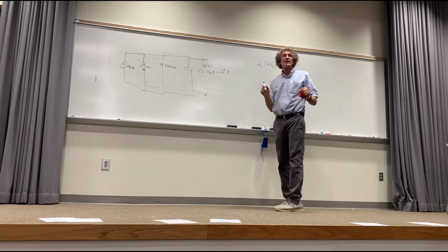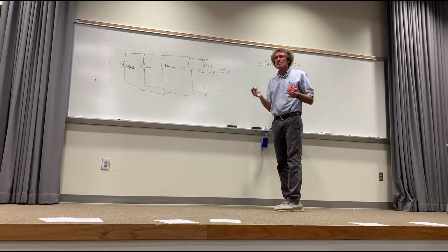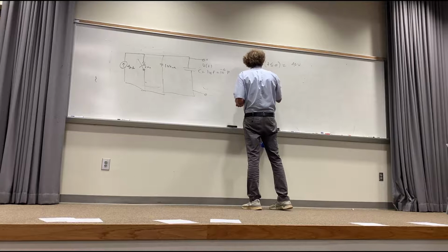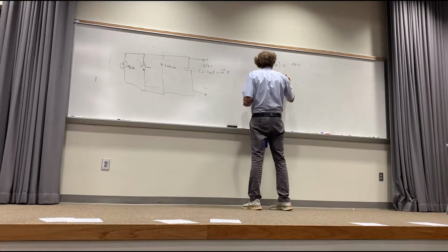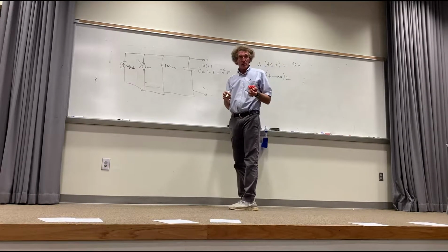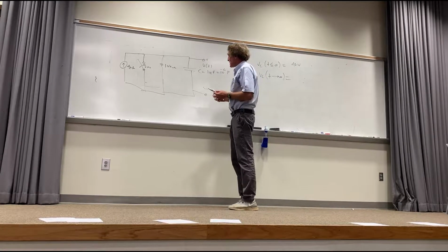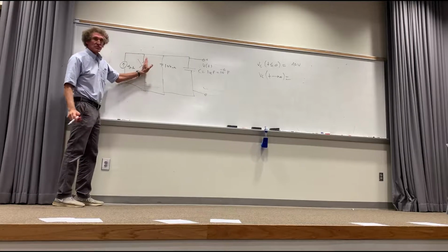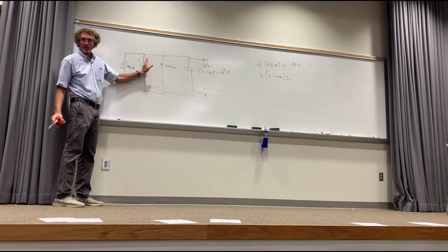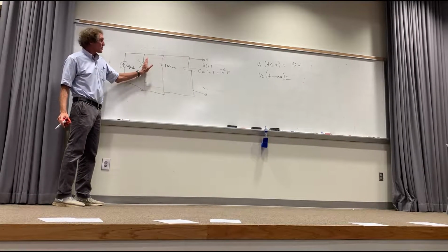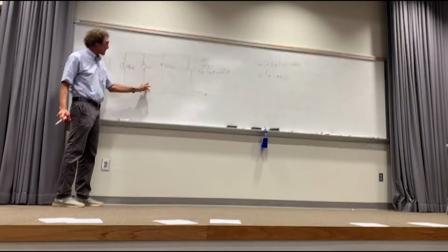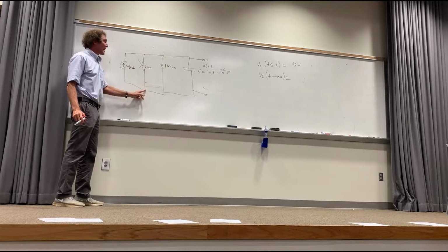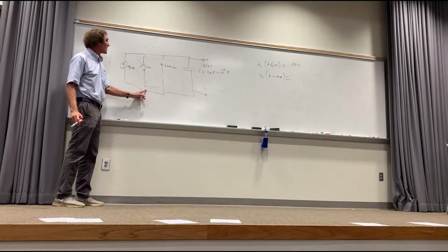Now, the next thing I'm going to do, and the order of this is not important, but for me, the next thing I do is find the voltage on the capacitor as t goes to infinity. All right, when t goes to infinity, what happens? Well, this is closed, right? Isn't that right for t greater than 0? When it's closed, what happens? It literally shorts out all this current. It just flows around here, doesn't it?